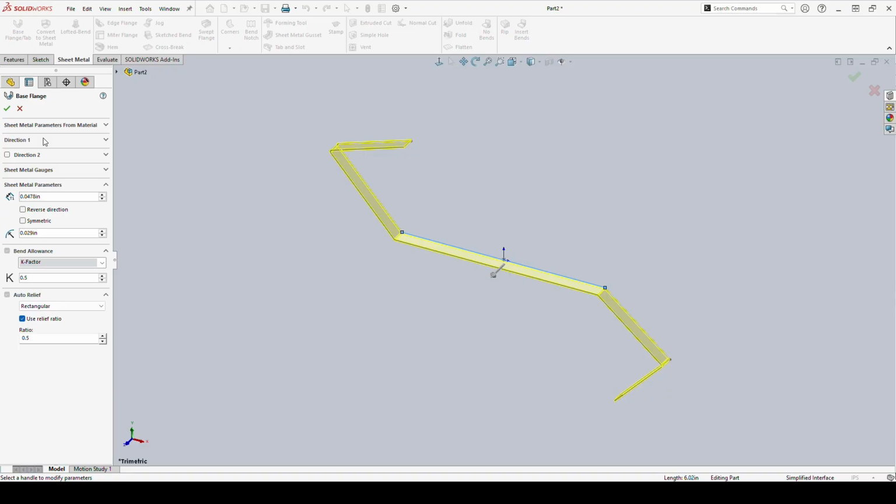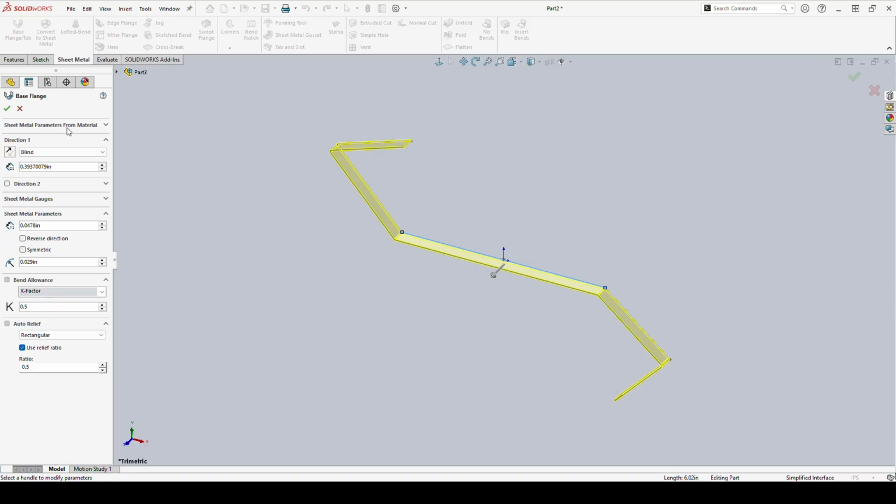So if you've got extra lines in there that you don't want becoming sheet metal, make sure they're hidden lines. With this, you're hopefully noticing that I've got a lot of the same components at the top because it's still the same command. I have a couple of extra pieces here. So these guys, well, not entirely this, but this guy right here was our thickness that we could set before. This guy up here is not that thickness. That is how wide we want our sheet metal to be extruded to.